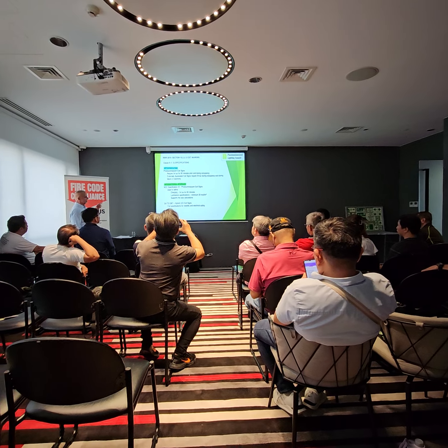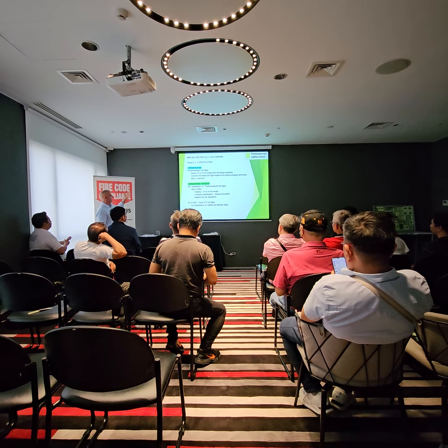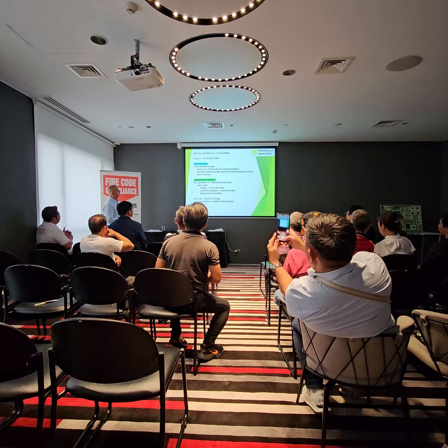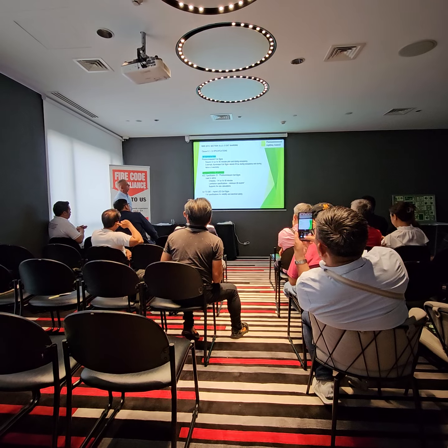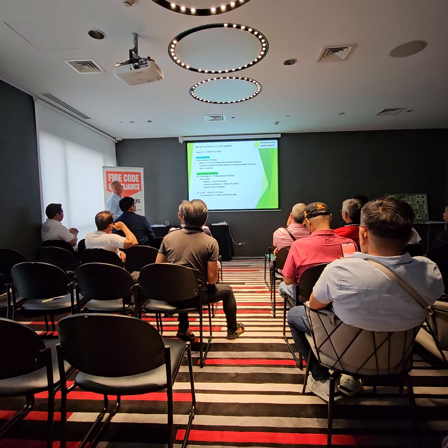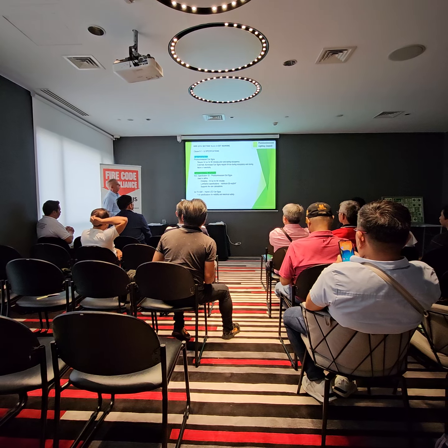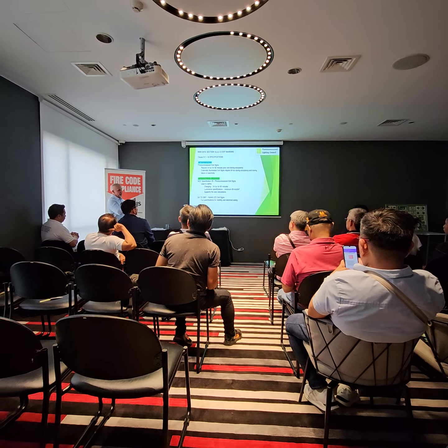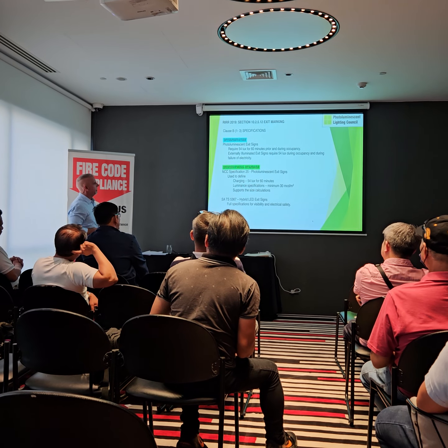Then clause B talks about the specifications of the sign. What are they made of? What do they do? So we've said, as I said, the passive photoluminescent exit signs require 54 lux for 60 minutes prior to and during occupancy. The externally illuminated signs, remember, they also need 54 lux on the face of the sign during the emergency. That's what makes them different. Photoluminescent, externally illuminated, two different things.